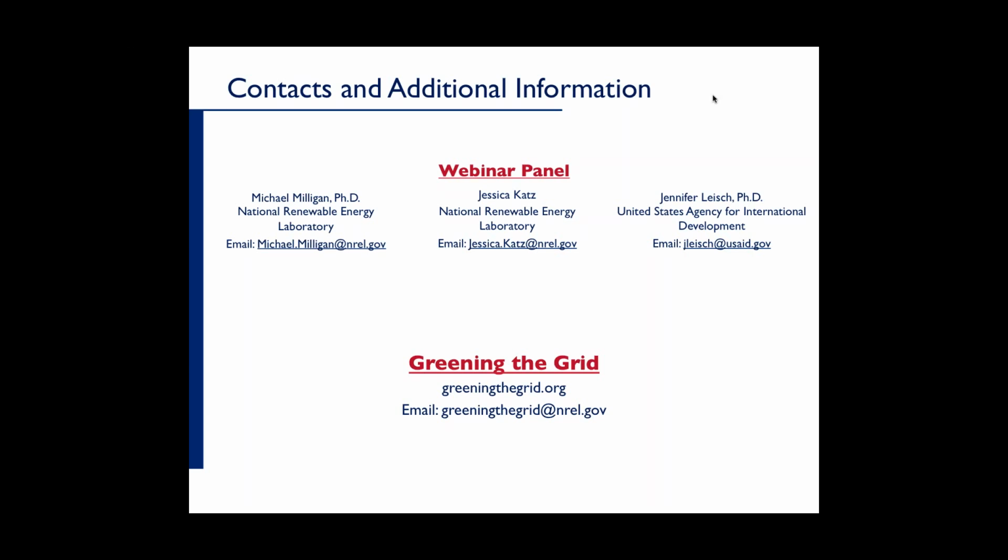The last comment I'd like to make about forecasts is that frequently updating the forecast can be a valuable thing, because as you get closer to real time, the forecast accuracy can improve. But at the same time, there needs to be some sort of an operator action associated with a new forecast. So for example, if somebody says, I can give you a pretty accurate 2 hour ahead forecast, the question becomes, what is the system operator going to be doing 2 hours ahead of real time? And if there's no system operator action that happens 2 hours before real time, that forecast may not be terribly useful.